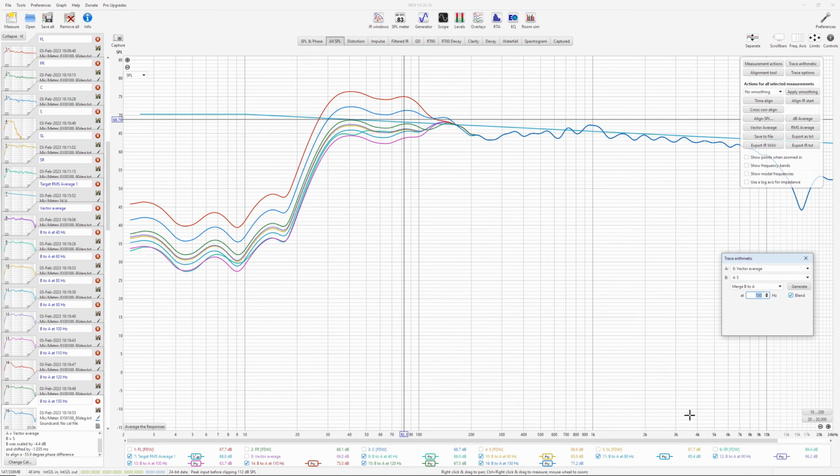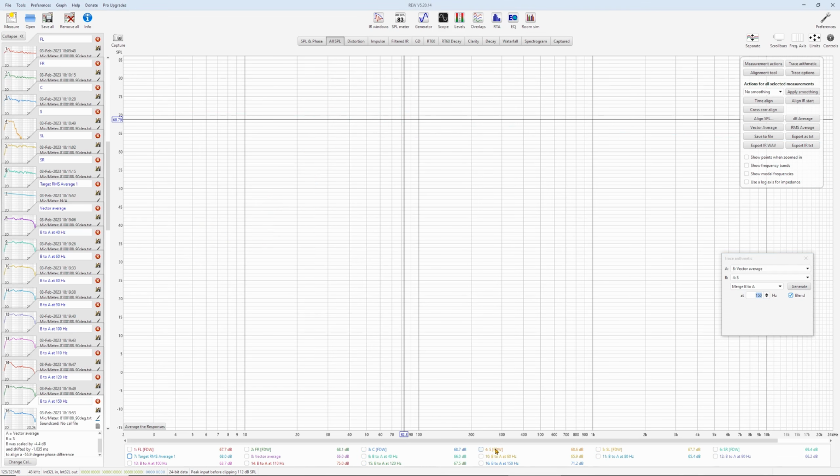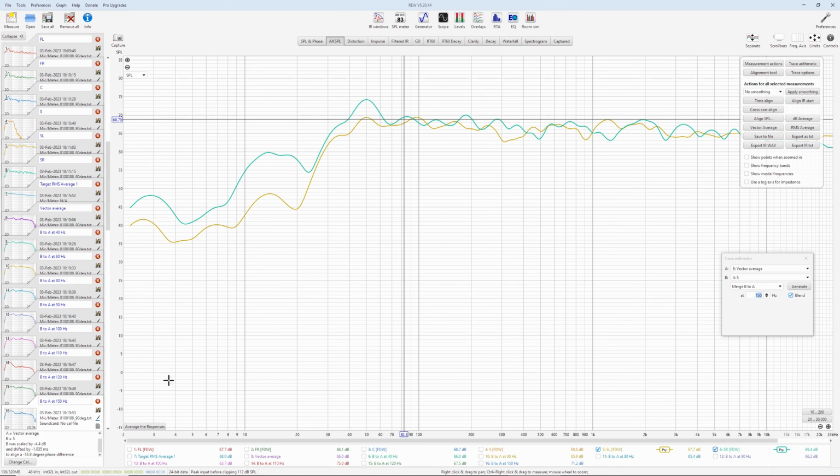Now let's do one more for the surround left and right. It'll be a bit more logical than my fronts. My fronts normally should be left alone and set at large, but I don't want to deal with their woofers. I want the bass to be managed by my subwoofers only, which has a very smooth response. There is a miniDSP working there. Anyway, surround left and surround right selected, vector average.